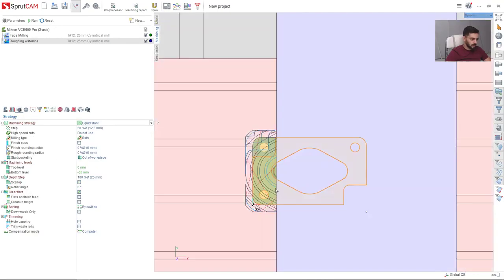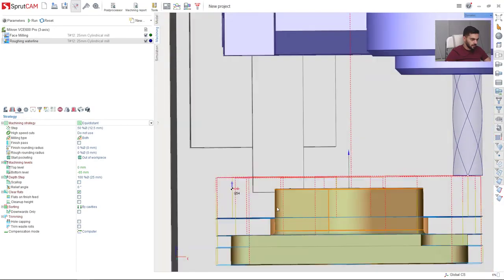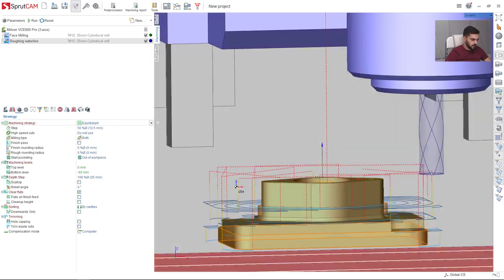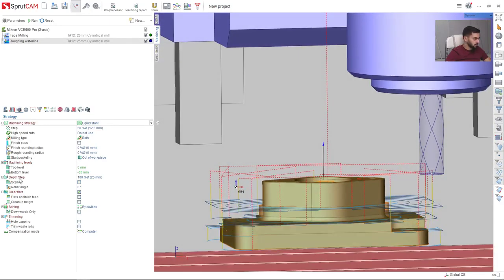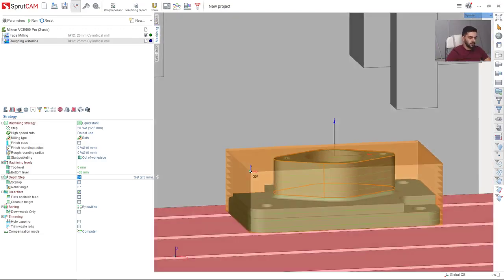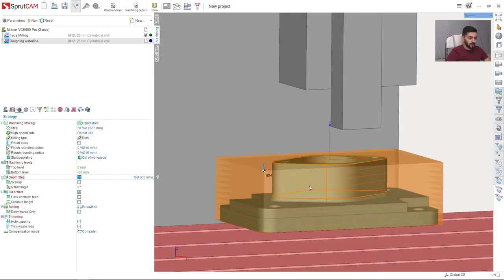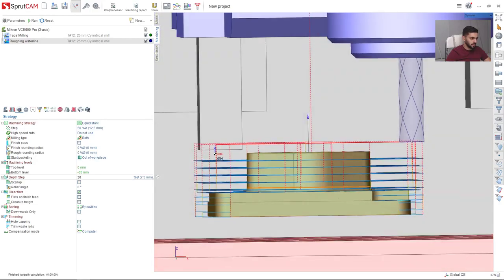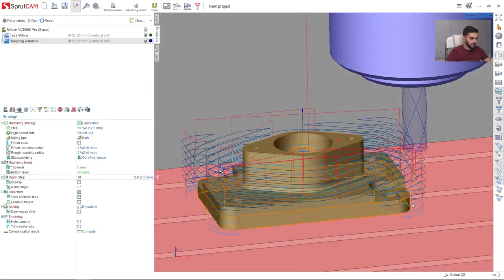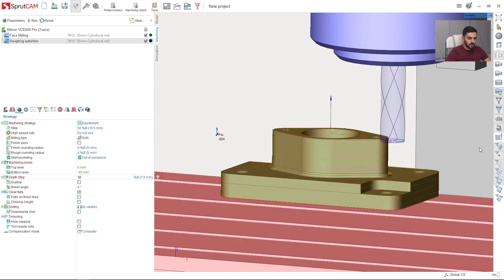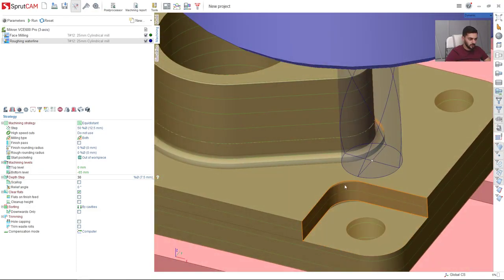So I can, for example, change the depth step for this roughing waterline operation. So here's the depth step. It is now 100% of the tool diameter. I will set, for example, 30%. As you can see here, we have the scratch of the toolpath. I will just recalculate. Here's our new toolpath.